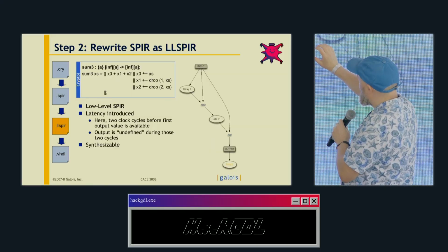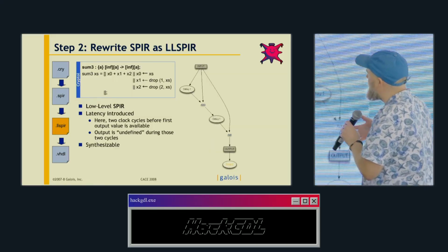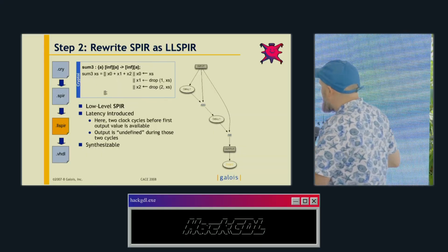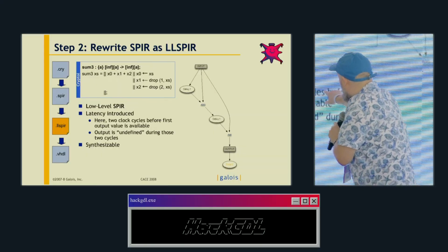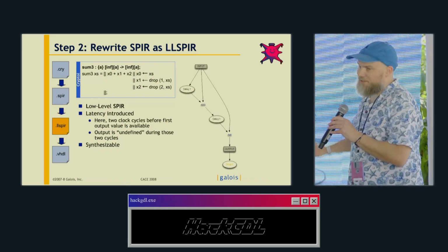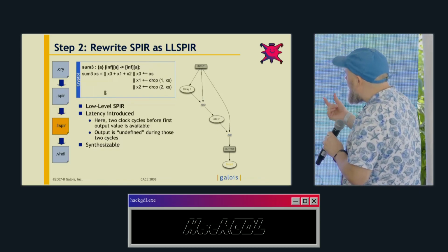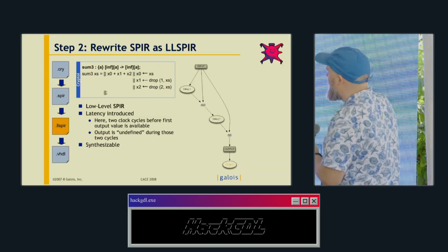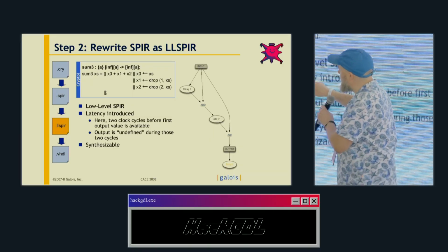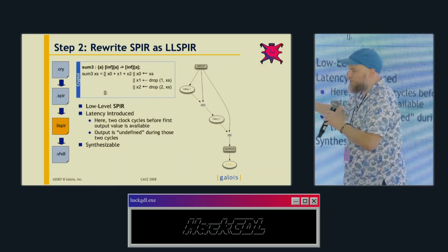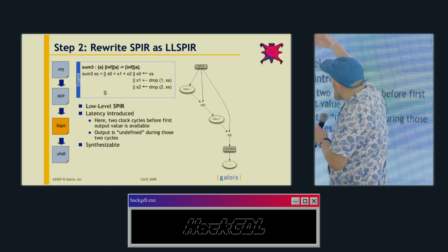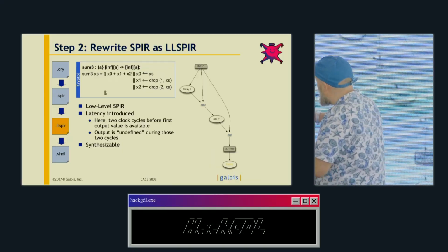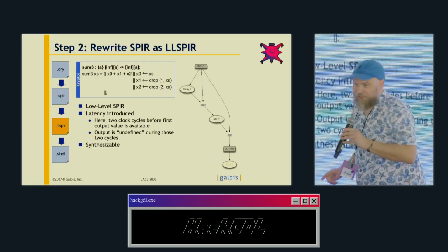So when you have these recursive functions or value equations, you try to map them into something which is implementable in hardware. And you want to extract some kind of clocked circuit out of it. And in very short terms, this is what the Cryptol compiler does behind the scenes. So you have this signal processing intermediate language. You're going to the next step where you're introducing things like these delays. And finally, you can go to some code.